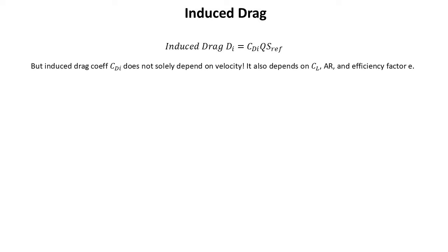In one of my last videos, I quickly glossed over the topic and accidentally incorrectly stated that the induced drag increases with velocity, so here's why that's incorrect. If we're generating the same lift, so that would be a condition of maintained altitude flight, and increasing airspeed, CL will be decreasing with the increase in Q. If a plane or a lifting body increases speed while holding a constant altitude, the only way for the lift to stay constant and not increase in altitude would be if alpha decreased, which is just decreasing CL.